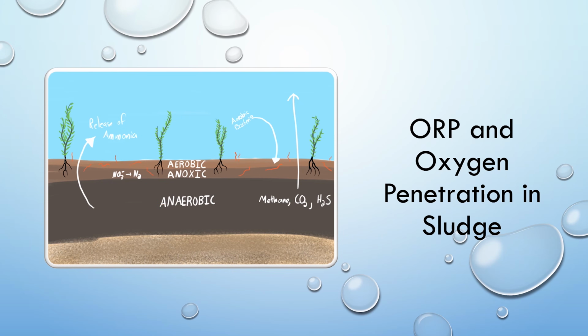So in the sludge layers, only that very top few centimeters, this lighter brown here, is considered to be aerobic, and that's in a good case. The darker brown area underneath it is the anoxic layer. The bulk of the sediment height, this dark brown, is anaerobic.